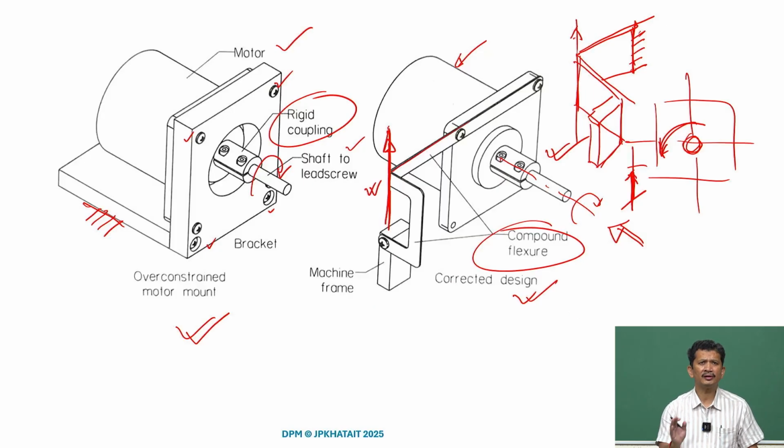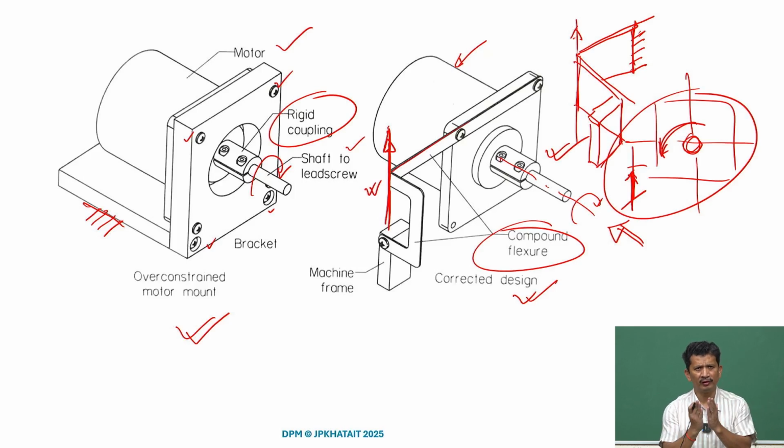So, not necessarily do we have to use many parts or a lot of tooling or do precise adjustments with a lot of jigs and fixtures. Sometimes if we understand the requirement, in this case a simple folded sheet with a sharp bend will do the job.